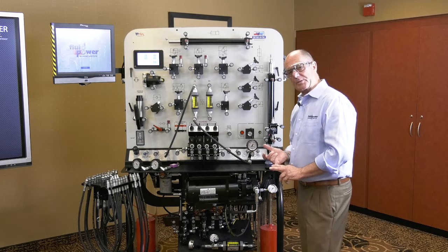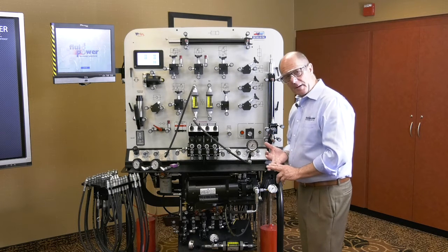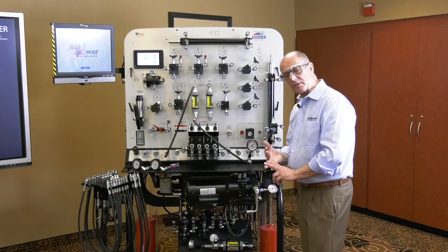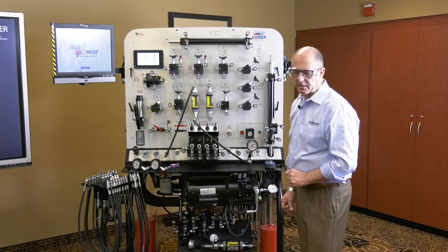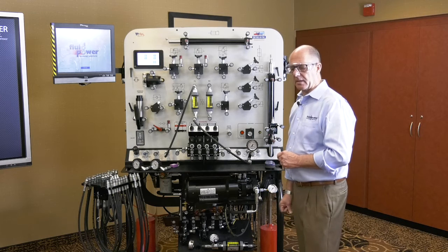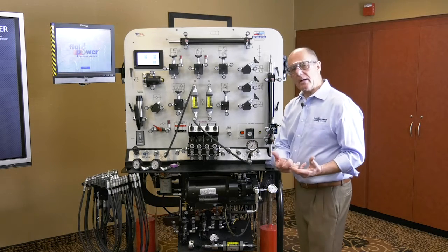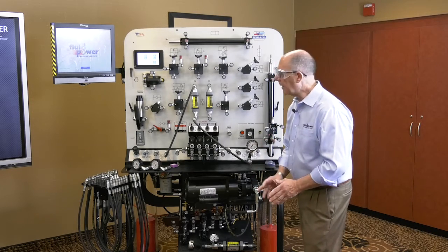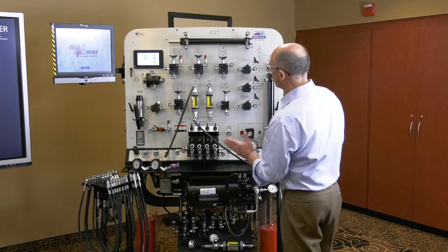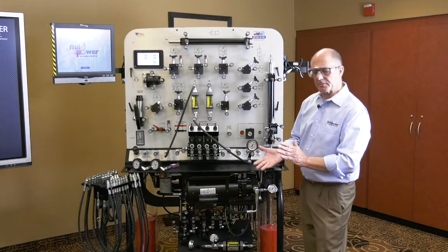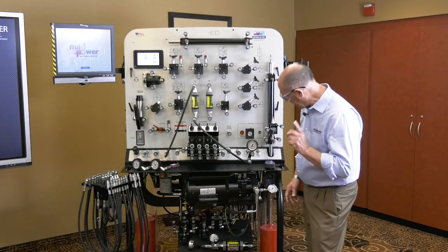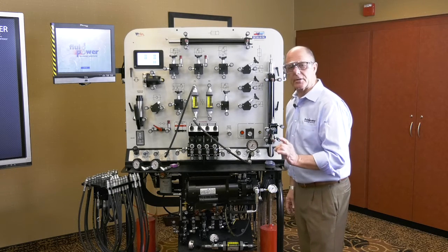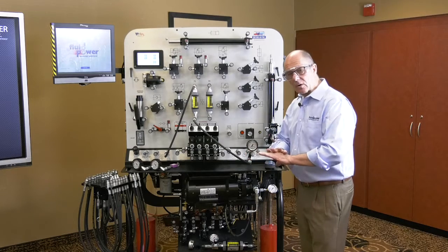This is an axial piston pump. According to rule of thumb, the maximum inlet restriction is 4 inches of mercury at 135 degrees Fahrenheit. What we did was we started the pump operating at rated flow, with the temperature of the oil right now at about 68 degrees Fahrenheit, so it's only going to get better as it heats up, but the inlet restriction point of reference is 3 inches of mercury. So that's what we've established.